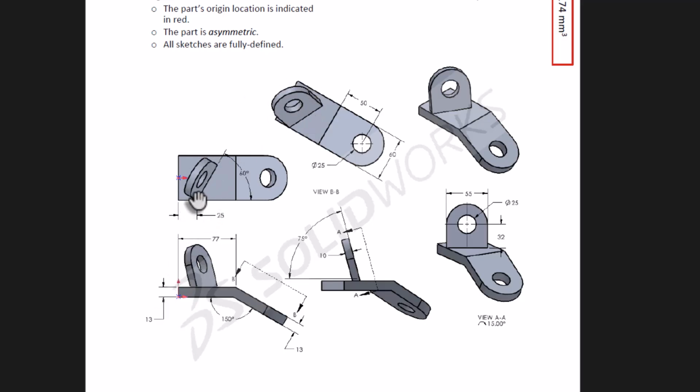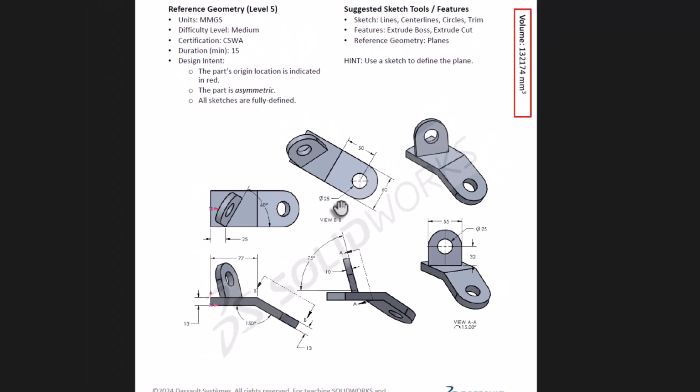From here we are going to draw some reference point and then we are going to create the inclined plane. Now for this inclined part you can also consider a single sketch. Here 77 can be considered, but then after 50 plus we need to consider this additional 30. So total we need to add of 80 millimeter. So either we can go in that way or we can create the external plane.